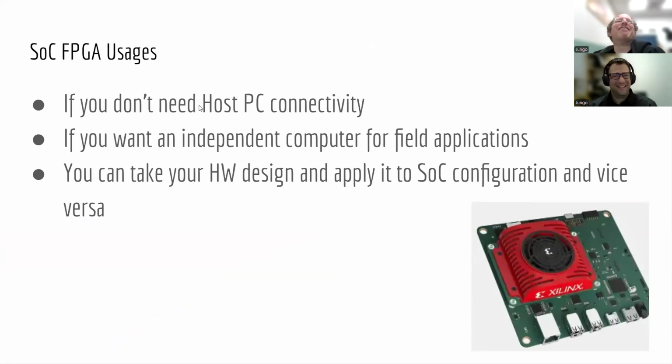I know you're smiling. But if you don't need host PC connectivity, then that's a good time to use a SoC. If you want an independent computer for field applications, you don't need a huge computer to put this huge evaluation kit on. This is actually a pretty small machine. And the good thing, and that's not something new, is that you can take your hardware design and apply it to SoC configuration or PCIe configuration and just move it around. All you need to do is change the design a little bit to fit a SoC configuration or a PCIe configuration.